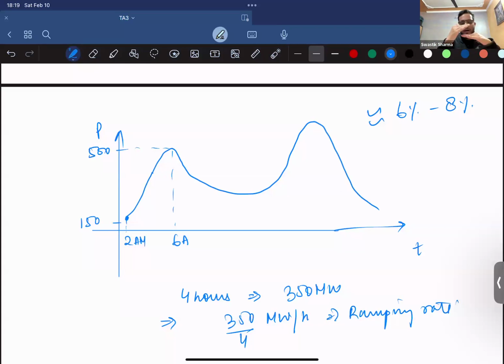That is, if you are a 900 megawatt power plant, just keep 50 or 100 so that you have the rest of the 800 to support the ramping needed for the huge load. So all the country had their hydro powers switch to a lower megawatt range so that they can power the grid quickly. That's how we sustained that load.